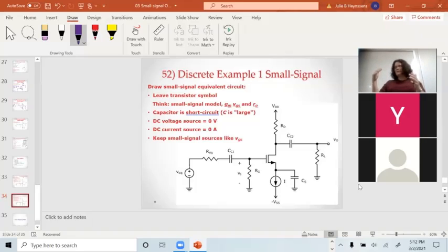The drawings show what order the layers are in the cross section. So given this top view picture of the circuit, you draw the side view based upon, okay, I've got pink here, so that's poly, and poly's on this layer relative to this layer. So you're basically drawing the cross sections.